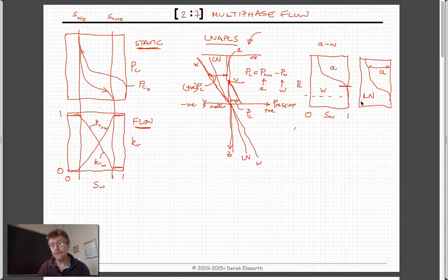that's not going to work out. Sorry. This has to be the capillary pressure increases. This has to be the NAPL in here, and this has to be the water that's here. And so this amount here, the difference between those, suggests that the saturation at this point has to be large saturation of the light NAPL that sits here. That's just supernatant, if you like, sitting on top of the water, as if it was water in a swimming pool, but actually now is also held in place by the gasoline.